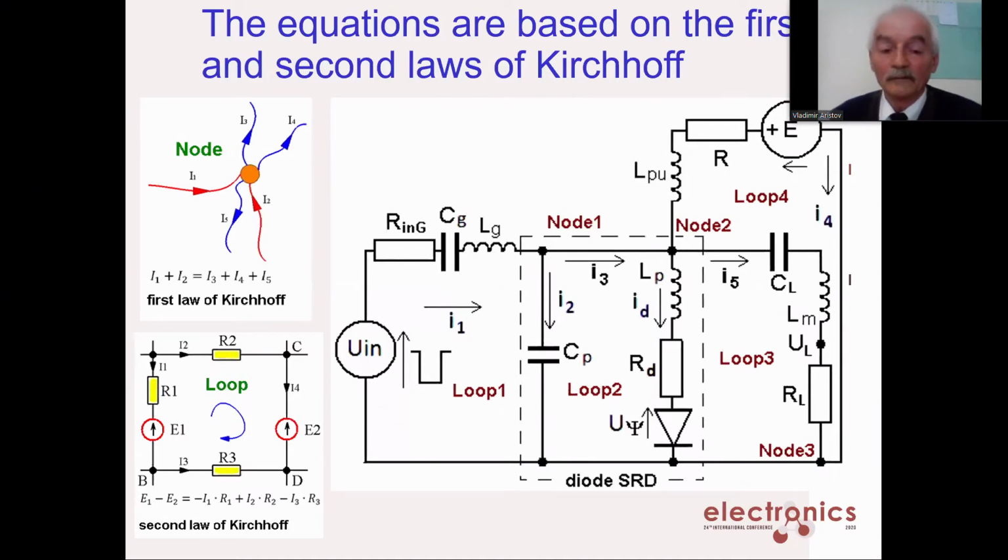First stage: the accumulation of charge in the diode, the supply of the input pulse, the dissipation of charge, and searching for the diode switching moment from a low resistance state to a high resistance one. Second stage: the processes of the first stage plus the diode switching and the formation of the desired voltages and currents. For each stage, based on the first and second laws of Kirchhoff, a system of equations was made.